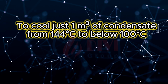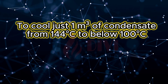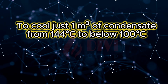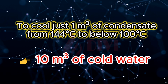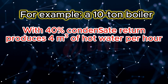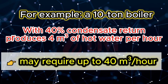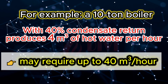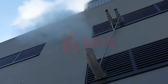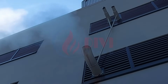However, in reality, to cool 1 cubic meter of condensate from 144 degrees Celsius to below 100 degrees Celsius without flashing, you would need about 10 cubic meters of cold water. For example, a 10-ton boiler with a 40% condensate return generates 4 cubic meters of hot water per hour, requiring up to 40 cubic meters of cold water to cool it. Meanwhile, the actual makeup water supply is only about 6 cubic meters per hour. This means a large amount of steam will inevitably be lost to the environment.